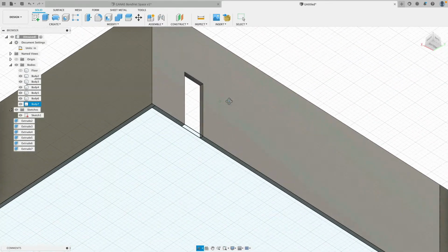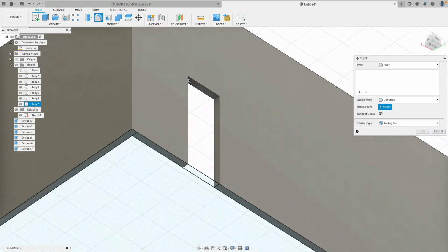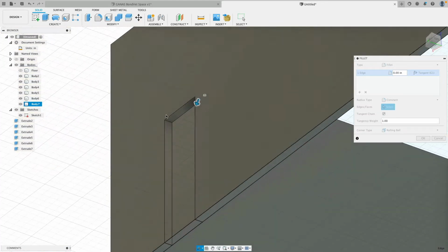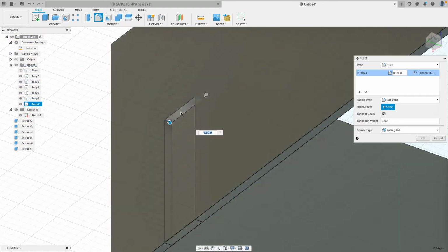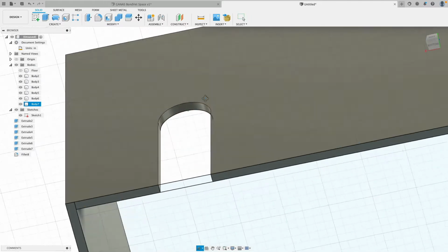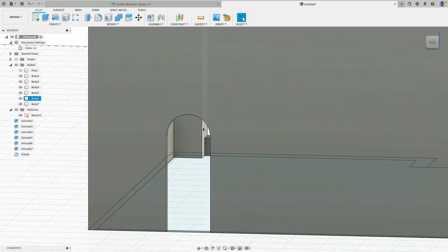Now we would like to have rounded arcs. That's actually very easy. We can select the fillet command, select these 2 edges. The inner diameter is 30, so the radius is half of diameter. So this is 15. Enter. And then we get a really nice round part.